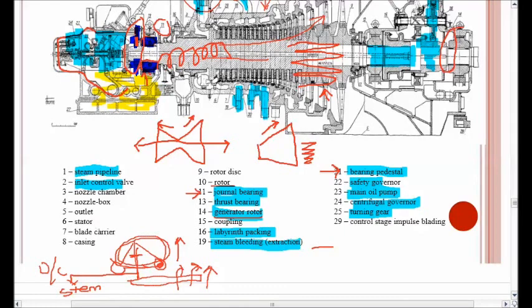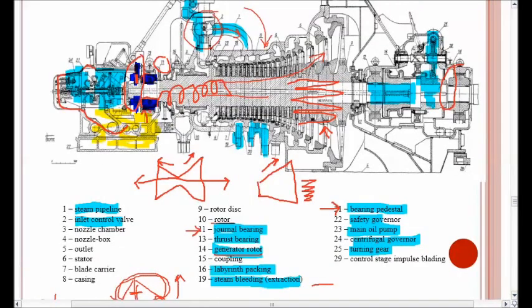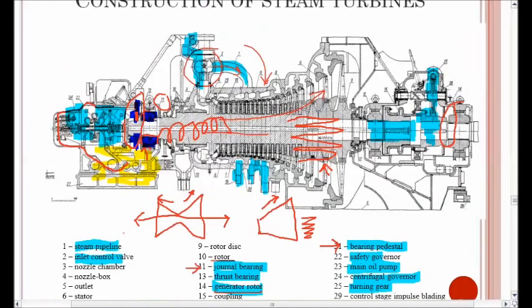To say precisely, centrifugal governors are the primitive type of control system that were used to control the speed of a turbine, and they are still in use in case any instrumentation or electrical interlock fails. The centrifugal governor will come into the picture to avoid any overspeed of the turbine.